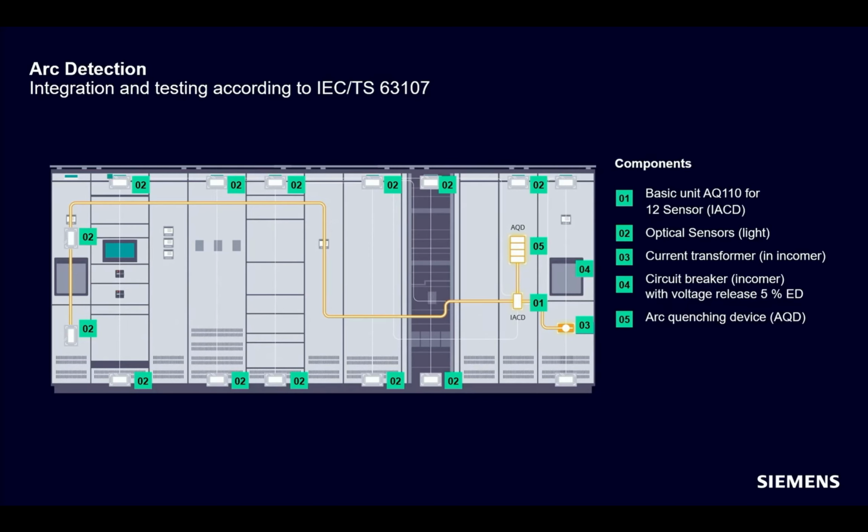In order to ensure protection, even in the event of an arc fault occurring on the primary side, in which case the CTs would not measure a current flow, there is also a special pressure sensor that trips the upstream distribution in medium or low voltage. To be able to reduce the stress even further, I would like to remind you once again of the pressure curve. This system can also be combined with a quenching device.